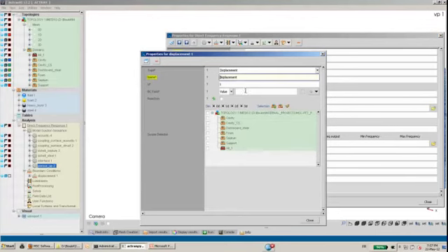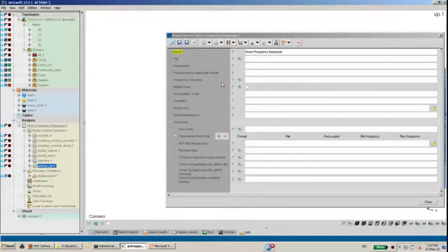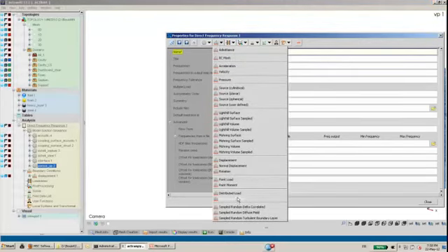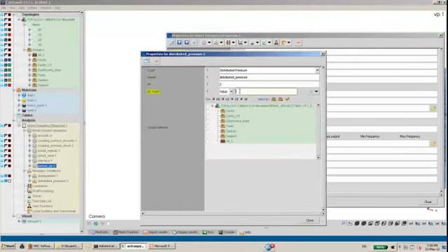First, the support conditions that will be a zero displacement in all directions for all the nodes of the edges of the dashboard. So here I say that I want zero displacement, and I will apply that to the edges of my dashboard. And then as an excitation, I will apply a constant and uniform pressure field on the dashboard. And so for that, I will create a distributed pressure that will be 1 Pascal uniform pressure, and I will apply that on the dashboard.